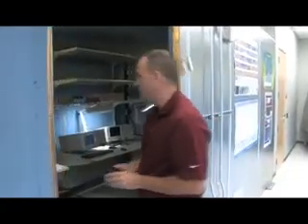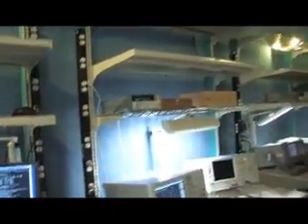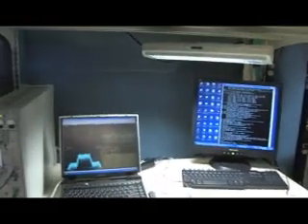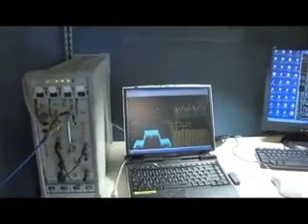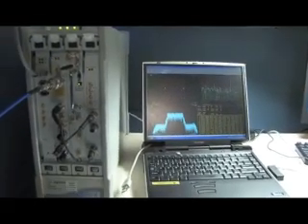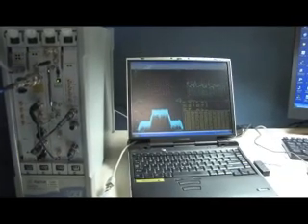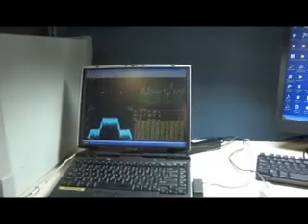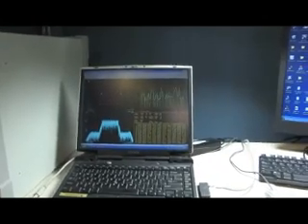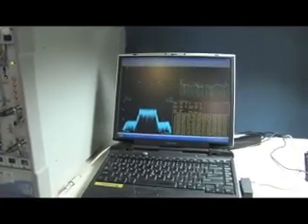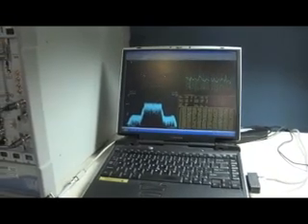So if we come inside the chamber here, we'll see I have a couple test stations set up. These test stations test our products at the board level. If you're looking at this first station, you'll see a vector signal analyzer. Now we have this vector signal analyzer attached through this blue cable to this box. And if you look at the screen right there, what we're doing is we're measuring some of the parameters of this radio. We're measuring frequency, we're measuring power levels, we're measuring modulation. And so we would use this box to do design verification for our products to ensure we meet our specs.